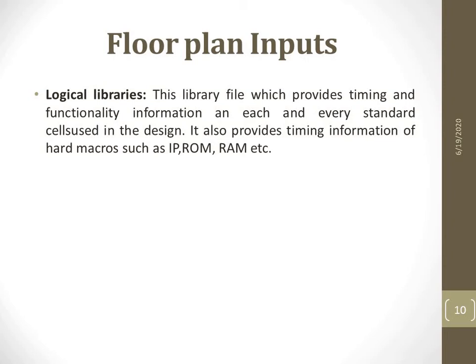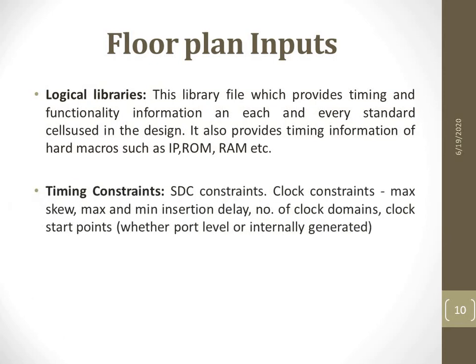So the next one can be from the logical libraries. This library file provides timing and functionality information on each and every standard cell used in the design. It also provides timing information of hard macros such as IP, ROM, RAM, etc. The other inputs are timing constraints.